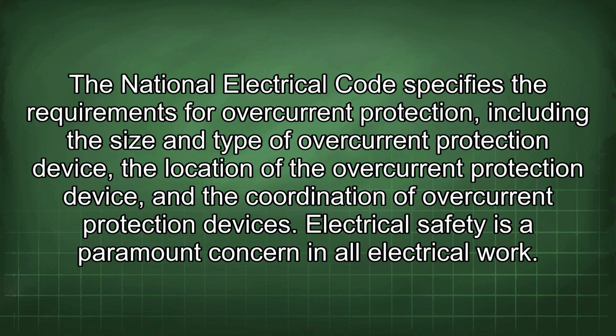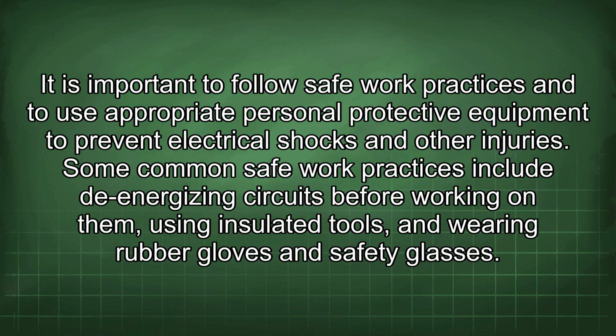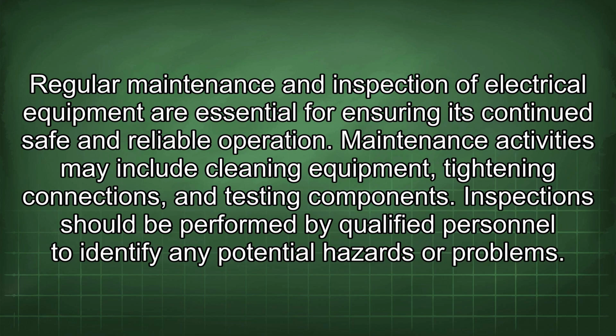Electrical safety is a paramount concern in all electrical work. It is important to follow safe work practices and to use appropriate personal protective equipment to prevent electrical shocks and other injuries. Some common safe work practices include de-energizing circuits before working on them, using insulated tools, and wearing rubber gloves and safety glasses.